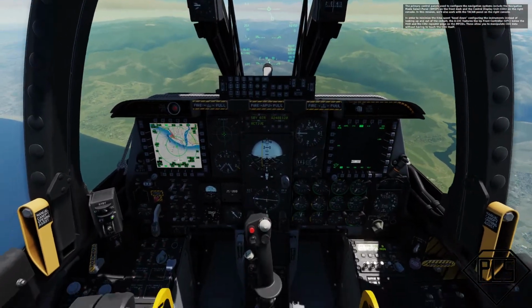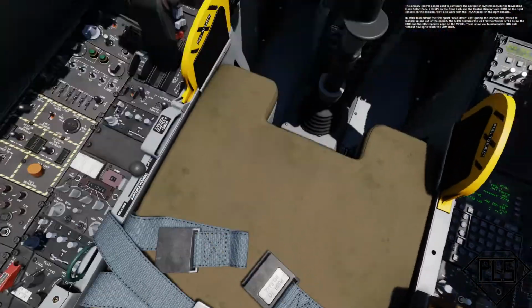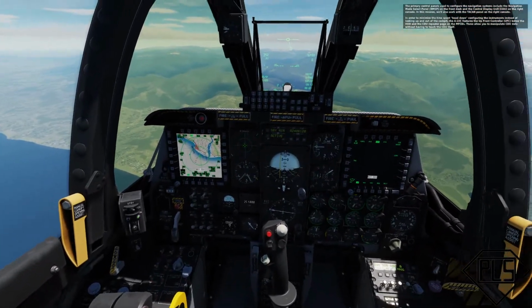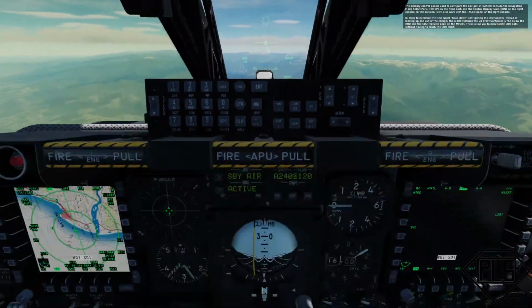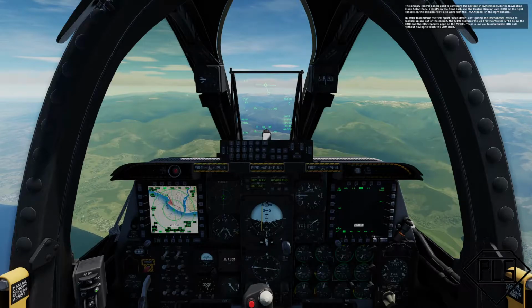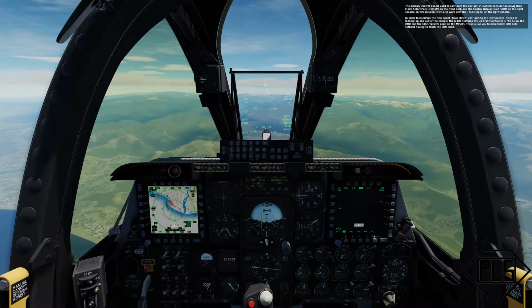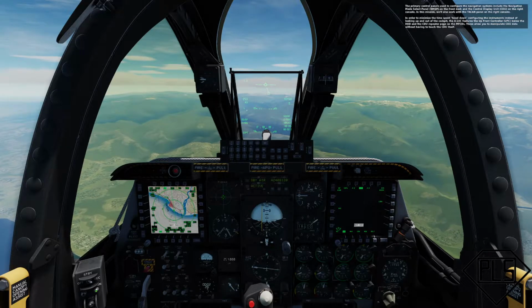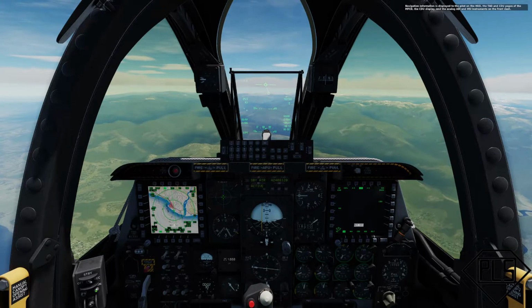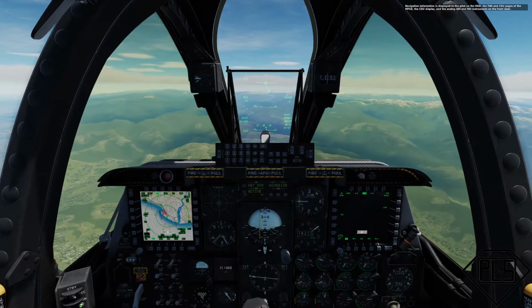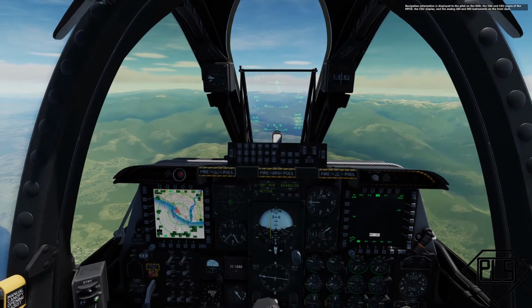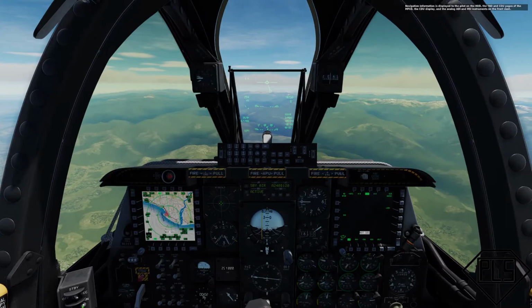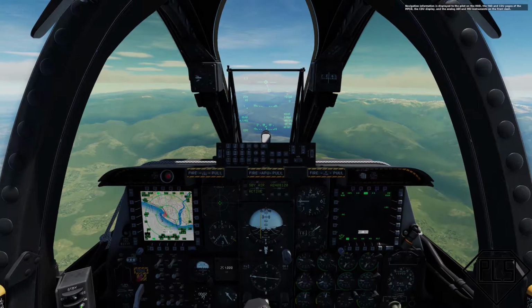In order to minimize the time spent head down configuring the instruments instead of looking up and out of the cockpit, the A-10C features the Up Front Controller, UFC, below the HUD, and the CDU repeater page on the MFCD. These allow you to manipulate CDU data without having to touch the CDU. Navigation information is displayed to the pilot on the HUD, the TAD and CDU pages of the MFCD, the CDU display, and the analog ADI and HSI instruments on the front dash.